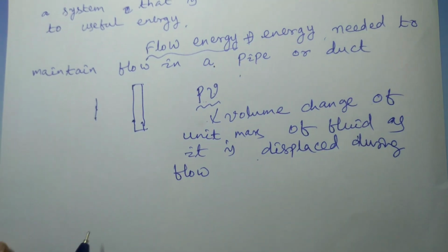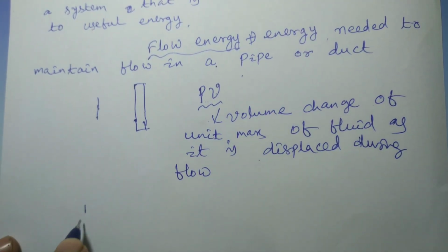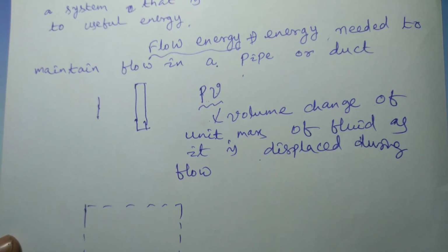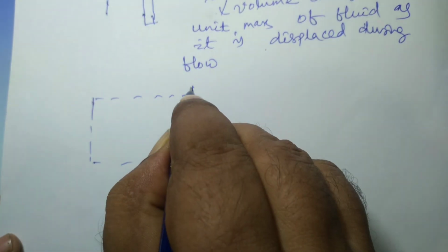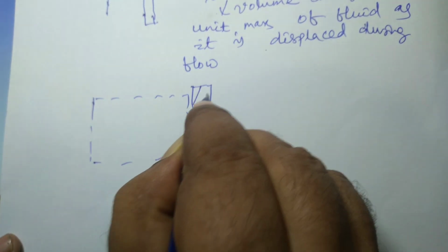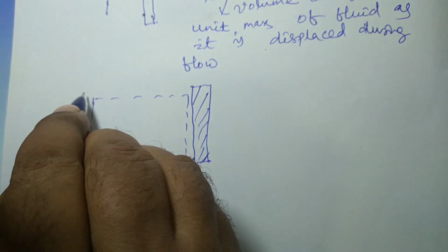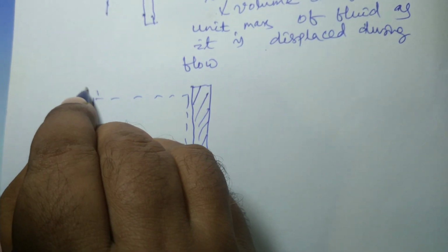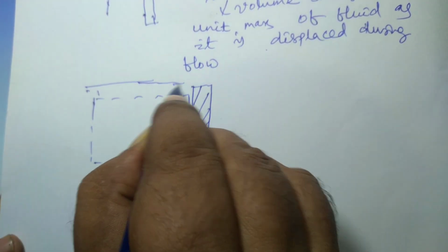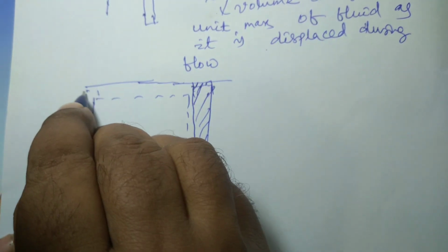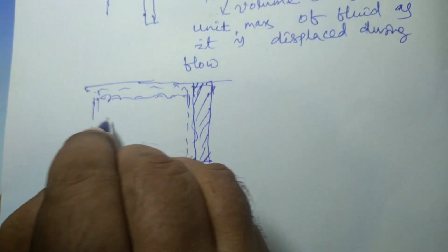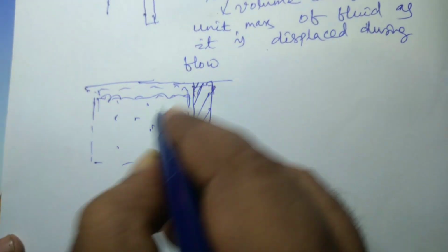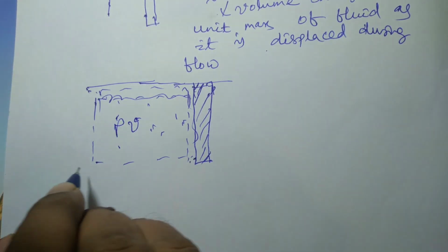So if we analyze, suppose this is your piston cylinder arrangement. Actually, there is no piston. This is an imaginary piston acting here in case of an open system. Suppose this is an imaginary piston which is analogous to your downstream fluid only. Suppose this is the boundary, and inside it there is fluid whose pressure is P and specific volume is small v.